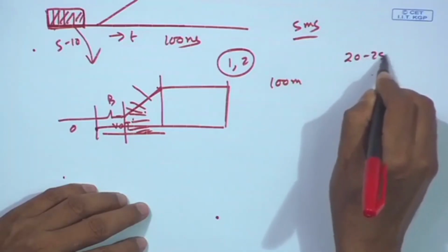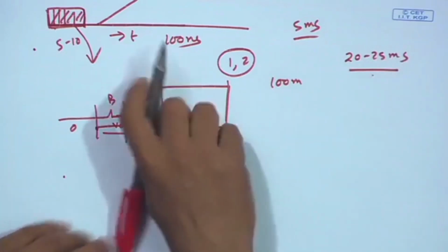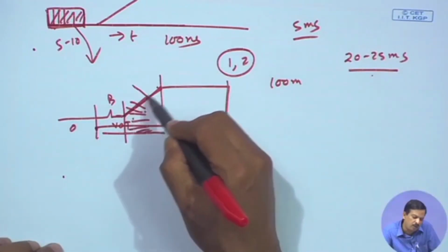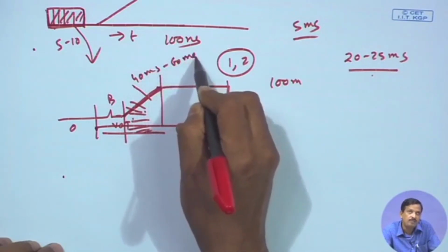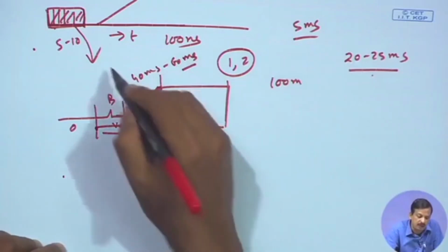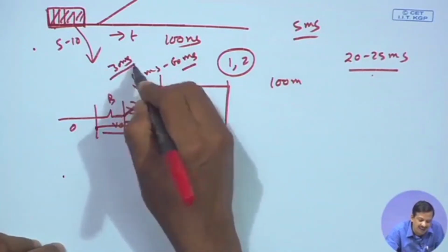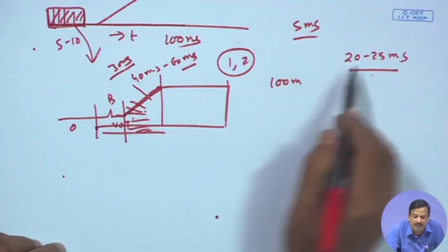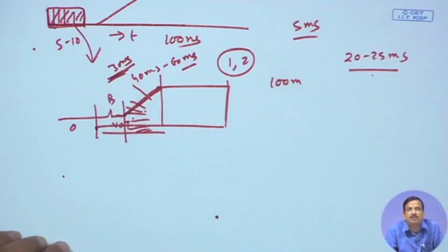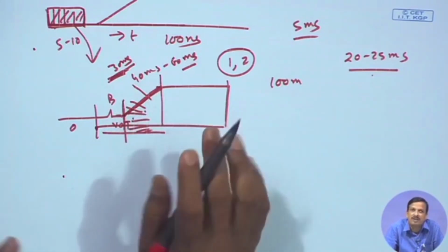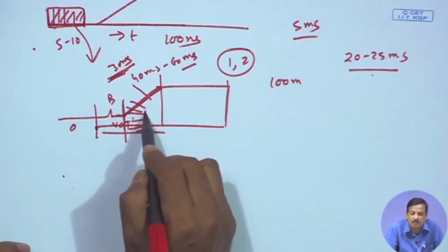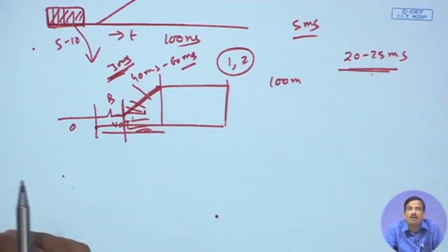So, I can say if I take a window of 20 to 25 millisecond, then one transitory period is roughly 40 to 60 millisecond, maybe even 30 millisecond for faster speech. So, at least I can ensure that my window length is lower than the transitory part. Okay. So, then I can say yes, I can find the detailed signal information along the time if I take a window length of 20 to 25 millisecond.